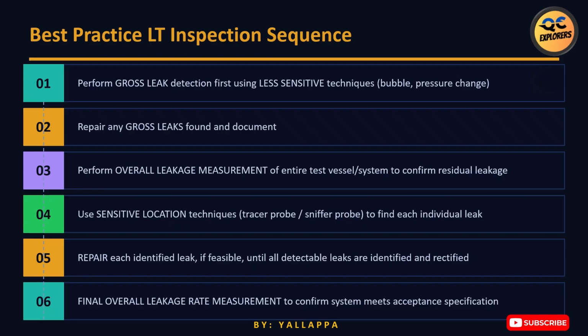Many candidates jump directly to the most sophisticated technique. That is not how professional inspectors work. Always start with gross leak detection, then progressively increase sensitivity as required.